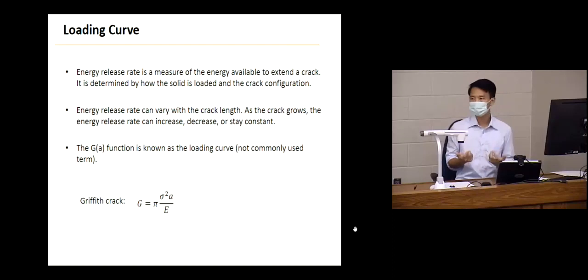We can change the energy release rate by how we change the loading, and it also changes as the crack grows. The energy release rate can depend on the crack length. It also depends on how you load the material, the crack geometry, and whatever we've done to the material.